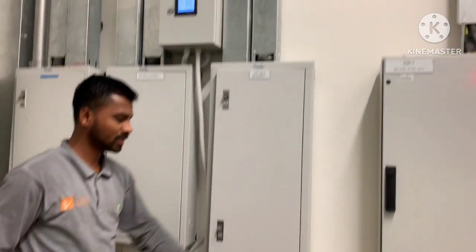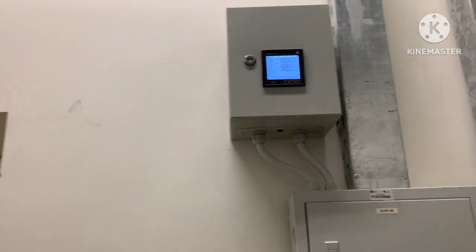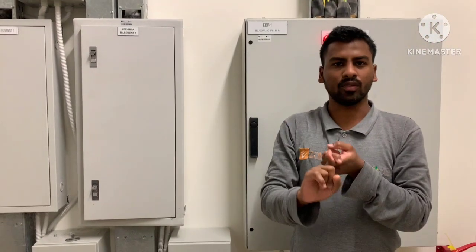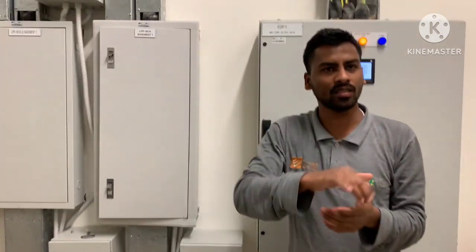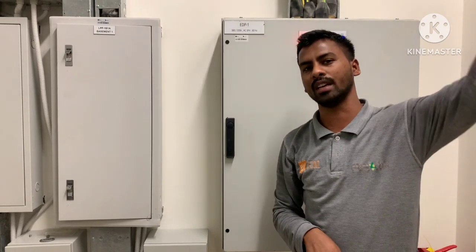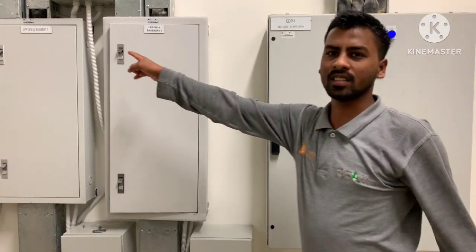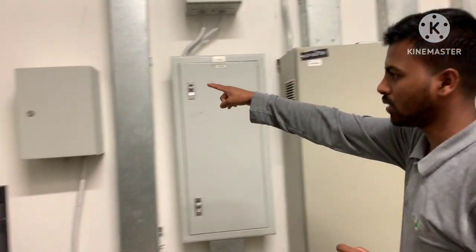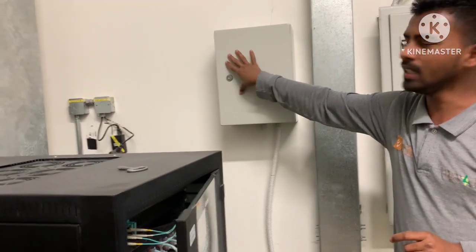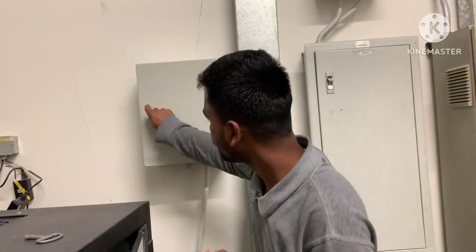Okay, so let me show you all these meters, 1, 2, 3, 4, and one over there, one over there. All these 5 meters are connected in one network in a daisy chain structure. It means the RS485 communication wire is coming from there, coming to this meter, then to this meter, then to this, then to this, and after this, it's connecting to one of our routers over there. This router is a Modbus to TCP gateway. Okay, this is the gateway. I will show you.